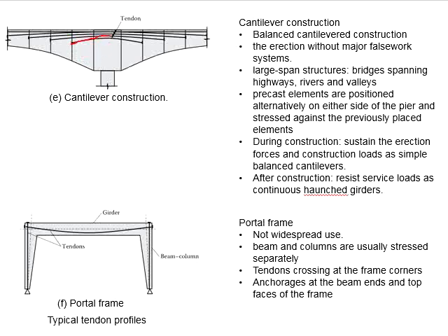After you have post-tensioned the member and this member will behave as one element, you will proceed with post-tensioning for the following segment. And now you will have another tendon connecting both segments. The same process proceeds for the next segment until the bridge meets at midspan of both piers.